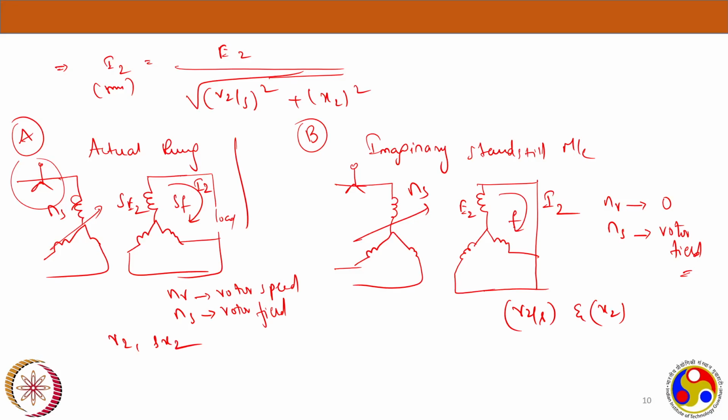That is the important concept here. Why we have imagined this, I will tell you, because we are arriving at the actual equivalent circuit of the induction motor. The main point is the stationary observer cannot distinguish the rotor fields between these two, because both will have the same speed, since the same rotor current is flowing through both machines, and the rotor field produced by both will also be of equal strength.